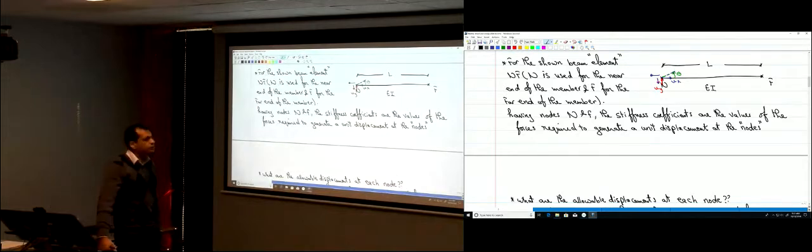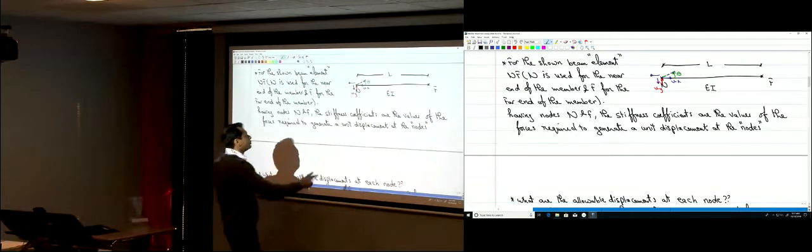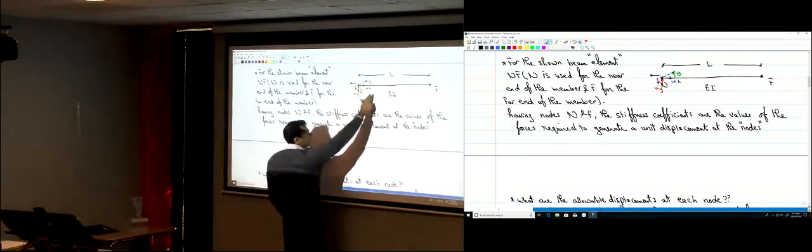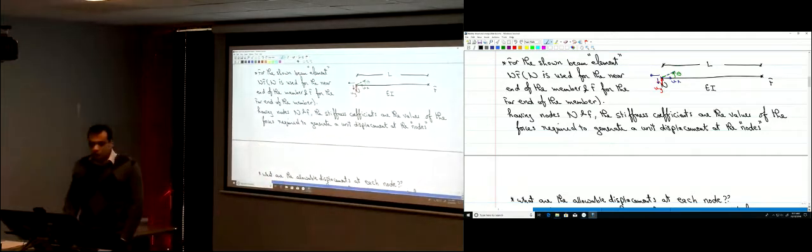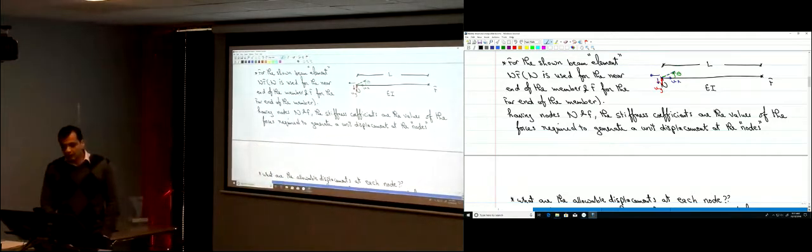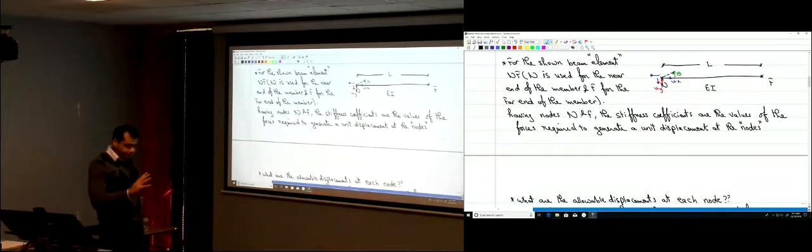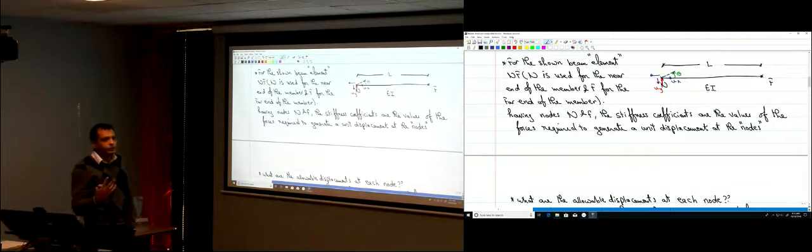We're starting our discussion with beams. So for beams, we're not taking into account the horizontal displacement Qx. So it's only a vertical displacement Qy, or we can call it delta. So here we have 4 different allowed degrees of freedom: 2 at the near end, the theta and the delta at the near end, and the theta and the delta at the far end.